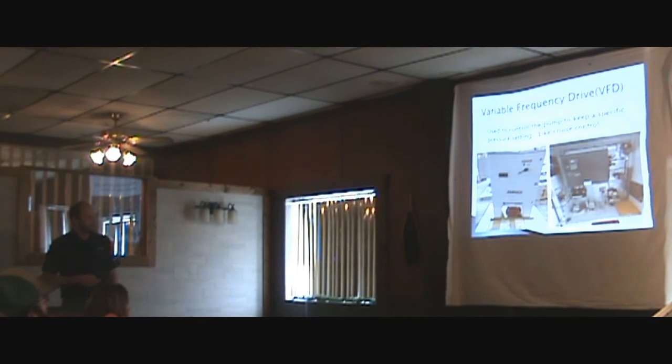And then the optimum choice obviously is a variable frequency drive. Just like cruise control is the best way to put it. You set a pressure and it just maintains that pressure all the time, no matter what the system's doing.